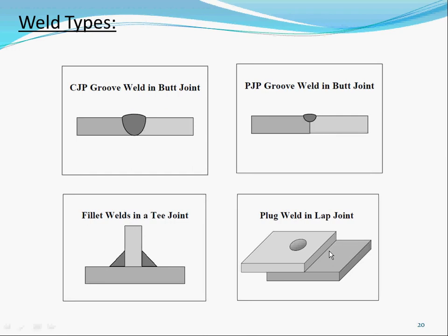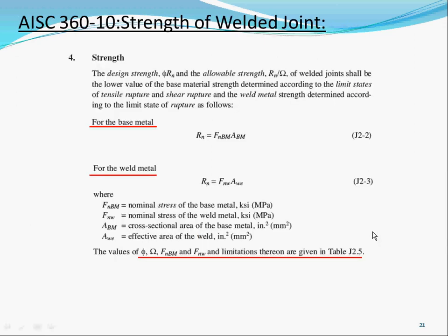And when you overlap it, you could either use a fillet weld here, a fillet weld on that side, or they use a plug weld to do both. And this is for very thin materials. They have machines that put a stamp through and they weld it this way.